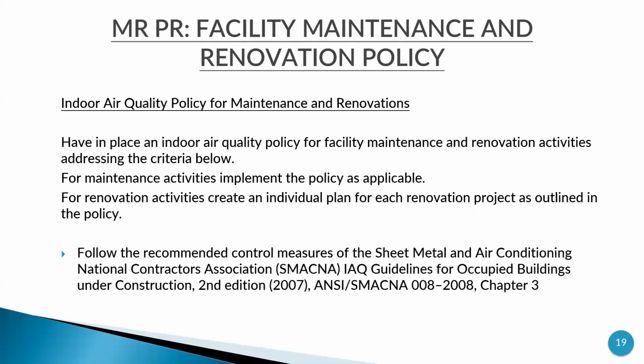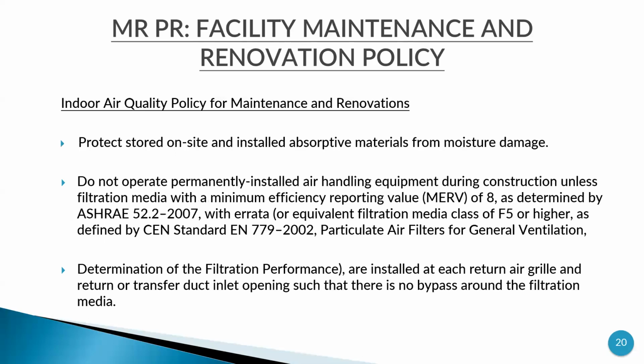Guidelines for occupied buildings under construction, 2nd edition 2007, ANSI/SMACNA 008, chapter 3. Protect stored on-site and installed absorptive materials from moisture damage. This is the second one. Third one, do not operate permanently installed AHUs, air handling equipment, during construction unless filtration media with a minimum efficiency reporting value, MERV, if you remember.